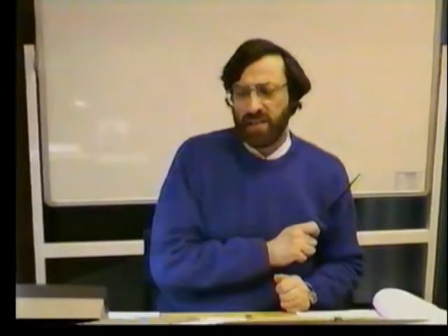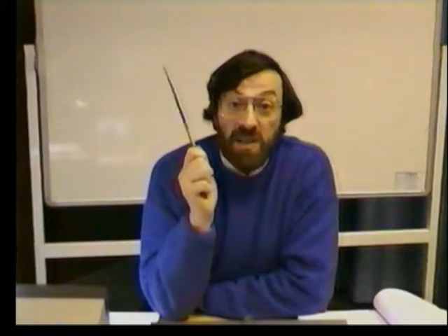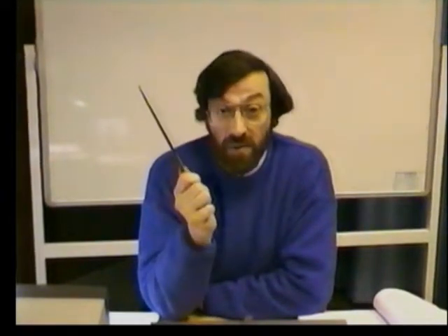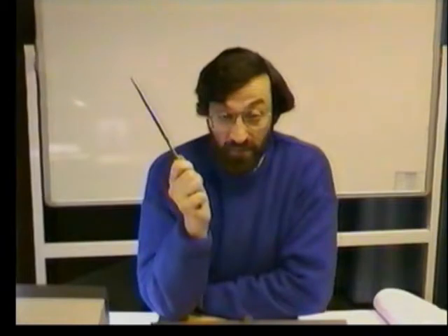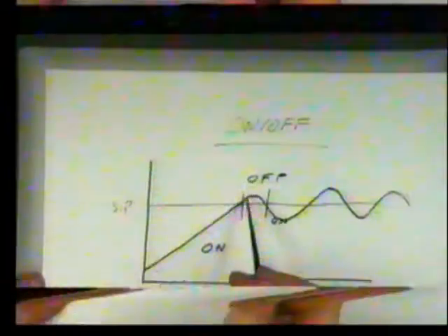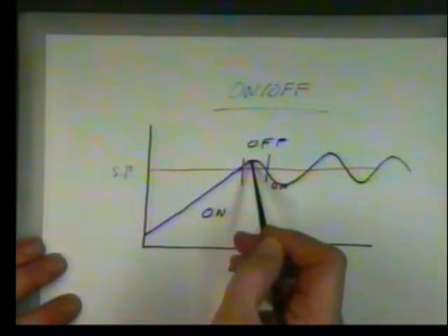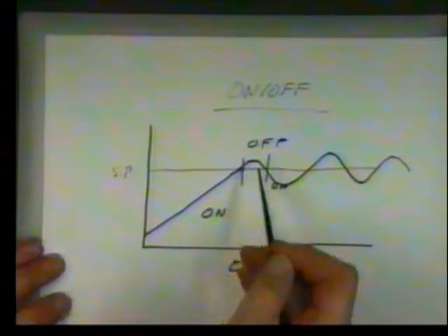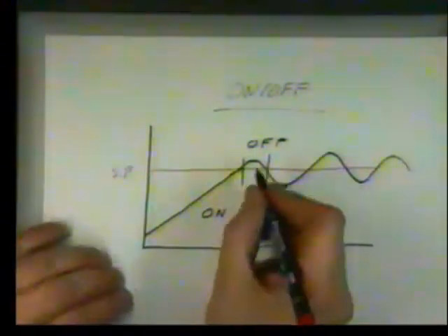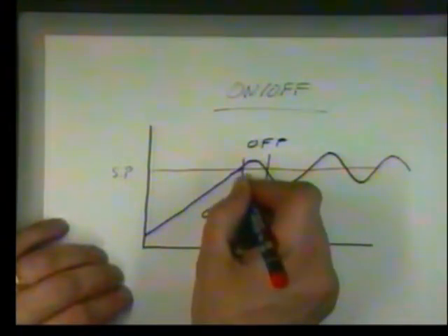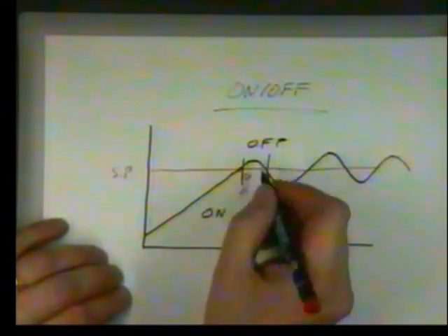Why do we oscillate? We do that because nothing happens instantaneously. In the real world, by the time you've detected the crossing, that's been converted by the ADC, that's been transmitted over the bus, and it's reached the processor, there is always a finite period of time taken to gather that data.